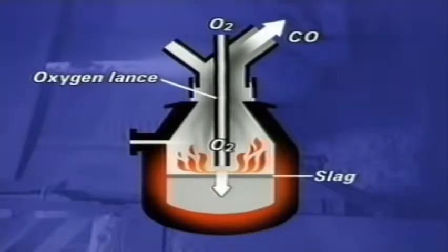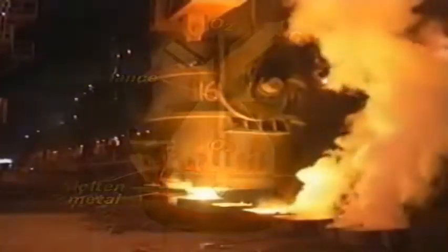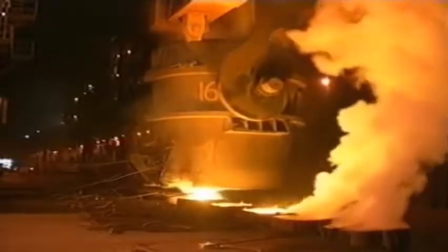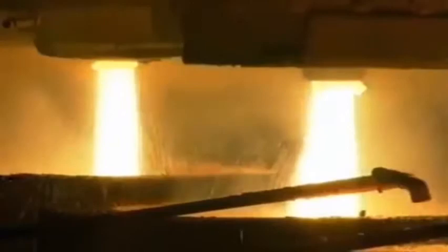The other oxides react with lime to produce slag. Molten metal is drawn off through a tap hole. After further treatment, the steel is solidified. One method is to use moulds to form steel ingots. A more recent method is continuous casting, where steel is poured through cooled copper moulds and drawn downwards by rollers. The resulting steel shape is cut into lengths. Rolling the steel produces the finished shapes required.